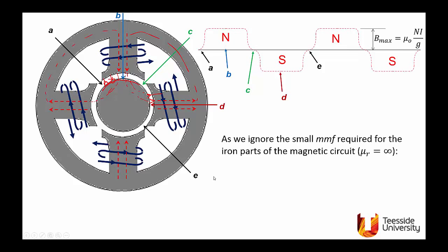We'll just say, if we ignore the reluctance of the iron, and I showed you a couple of slides earlier justification for this. You remember the case when we considered a flux path in the iron, which is 300 millimeter, and the air gap was 5 millimeter, and we found that if we ignore all the reluctance due to the iron, which has very high, several thousand, relative permeability, the flux calculations will not be affected too much by ignoring the reluctance of the iron.